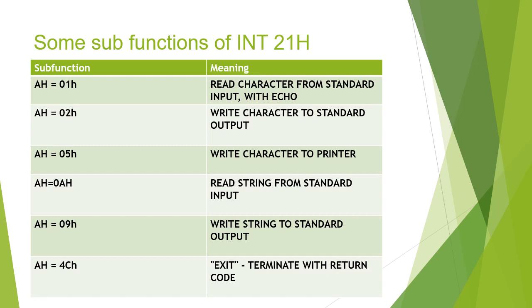So INT 21H is one of the frequently used interrupts for our 8086 application programs, since it provides you the DOS API, as I told already. There are sub functions actually. So in 21H, you will be reaching that part of the DOS API. You multiply 21 into 4, so you'll be reaching your IP address. The next word location will give you which code segment it is. Combining those two, you will be reaching that part of the DOS API. And in that you have sub functions.